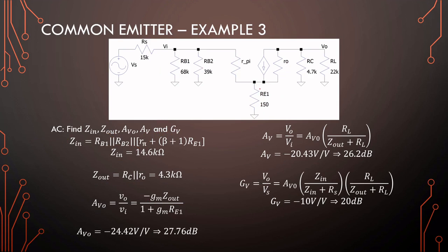It can take the voltage from the output or the current from the output and convert that information back to the input. And we know that feedback usually stabilizes gain, helps with linearizing amplifiers, and so on and so forth, increasing input impedances, decreasing output impedances.